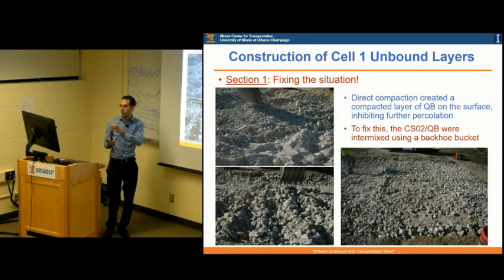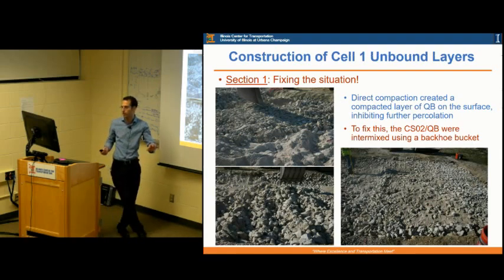Those quarry byproducts are reducing the direct contact between the large rocks. So they're reducing the shear strength of those layers, and they're acting like, let's say, a weak shear membrane or a failure shear, what do you call it?